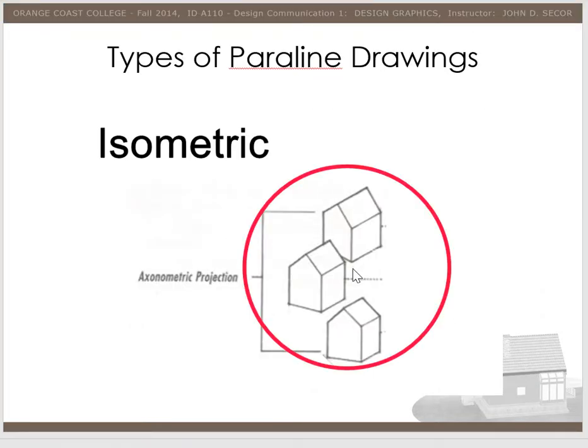And they show three different sides. There are different kinds of axonometric drawings, but the one we want to talk about is isometric, which means one. There's also dimetric and trimetric. That's three different sides. But this one deals with iso, meaning one. What it means is that there's only one angle used in the entire drawing, and it makes it completely even on each side. When you use a di, you use 2 different angles, which doesn't make the viewpoint equal. And when you use a tri, you use 3 different angles that create a different viewpoint altogether. But isometric, we're going to dive right into.